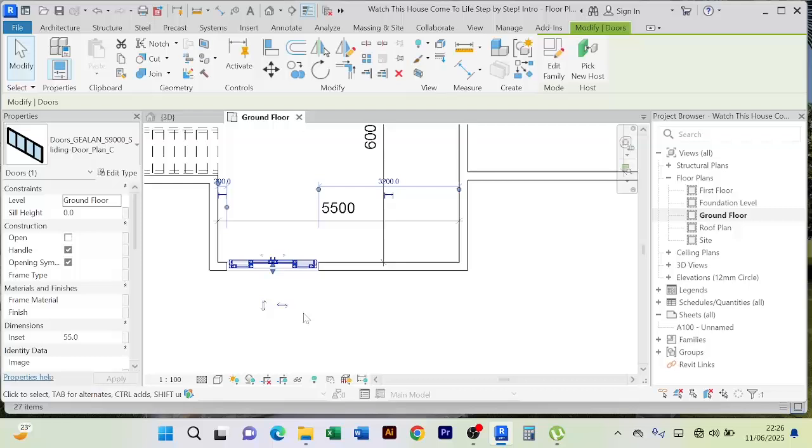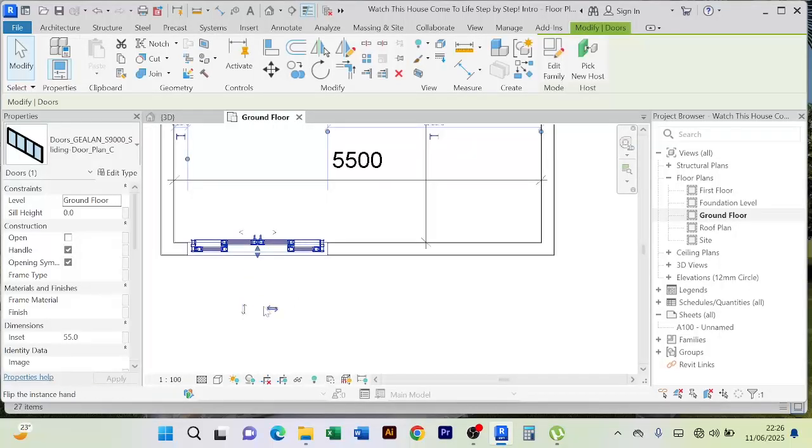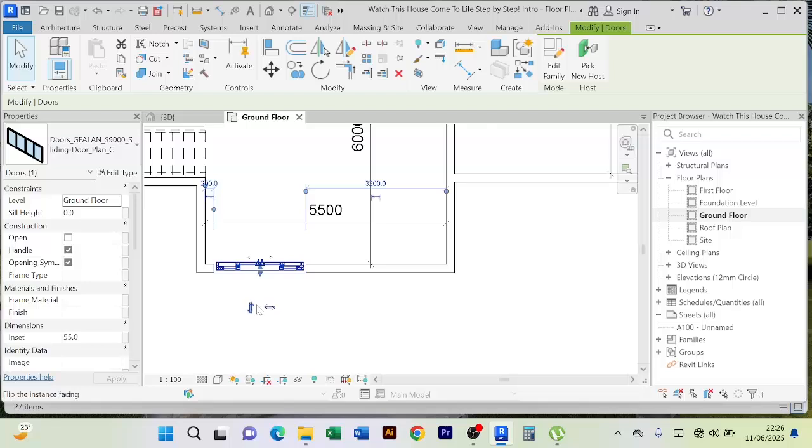Then when you click here, what you may not realize is that when you see these icons outside, that means this door is opening inside. But every exterior door has to open from the outside, and every interior door has to open towards the inside, unless the interior space has little room to open the door inwardly.